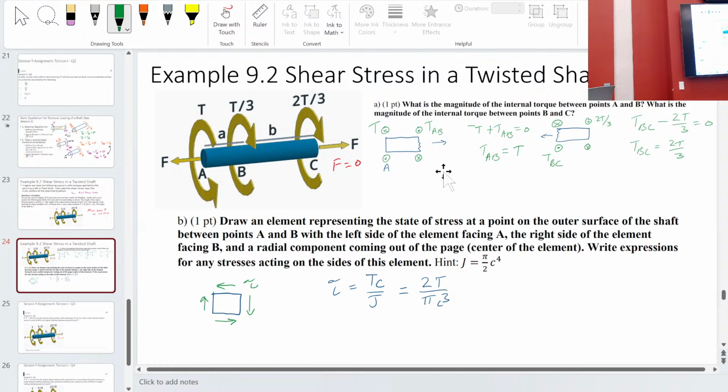Question that makes sense of applying the idea of the displacement of the center line. I understand how you use geometric patterns to arrive at this, but I'm not sure what the extra step I need is to find the change in that center line. Okay, so if you go through on a map, you can figure out what your strain is in the first region and the strain in the second. If I want the displacement to the right, and I know the strain of this side, I know the strain in this region.